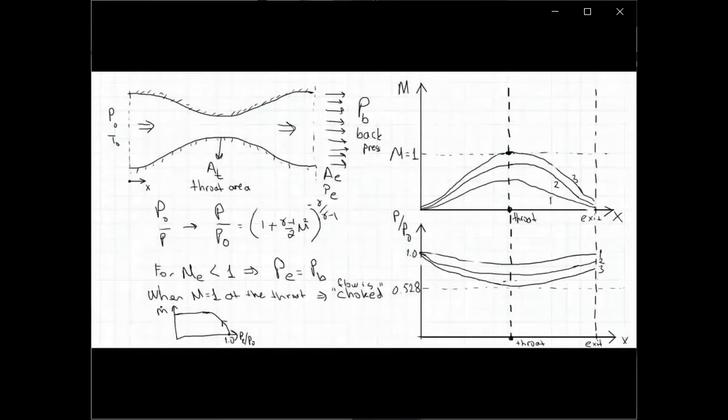As you keep reducing the pressure, mass flow rate on the y-axis will start increasing. It will increase and increase, and it will reach a maximum value, so m dot max. And then even if you keep decreasing the exit pressure, moving towards left on the x-axis, m dot or mass flow rate will not change. That happens after choking. So that's an important physical phenomenon as well.